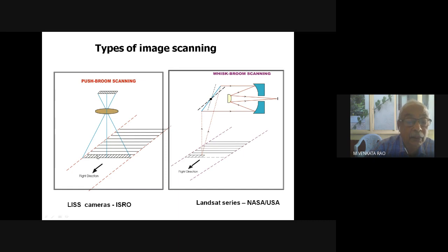So here, this is line scanning basically. That means as the satellite is going like this, each line is scanned at a time, and after the line, it will scan and go forward. Finally, the image is constructed by taking some number of lines into number of pixels. So you make a square area image, let us say, you construct this image on the ground.